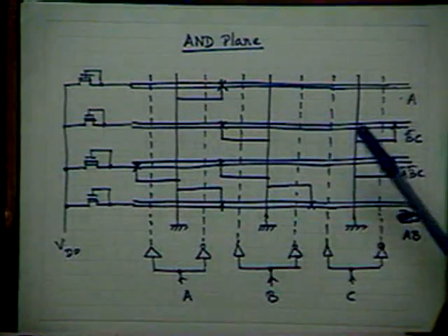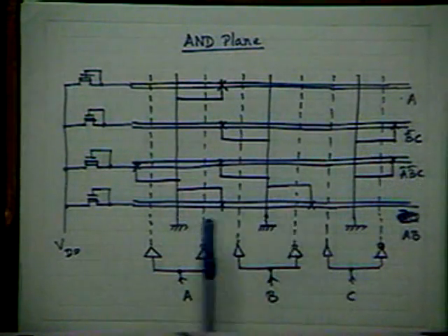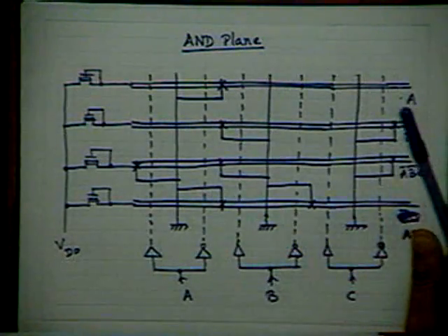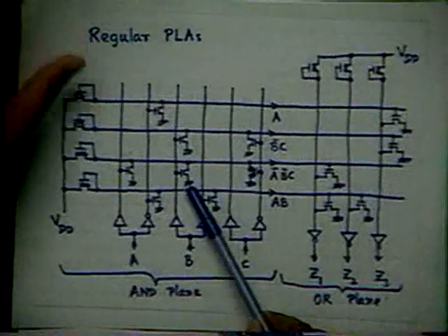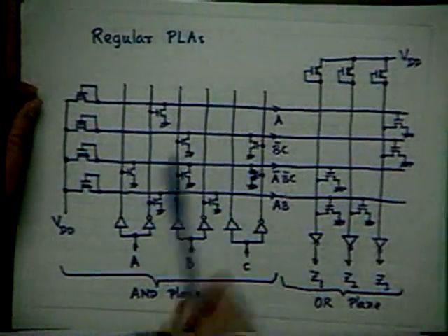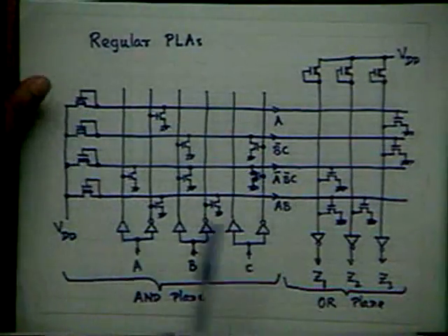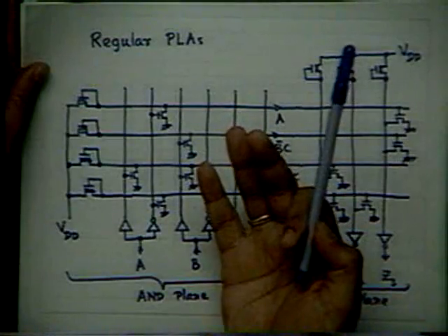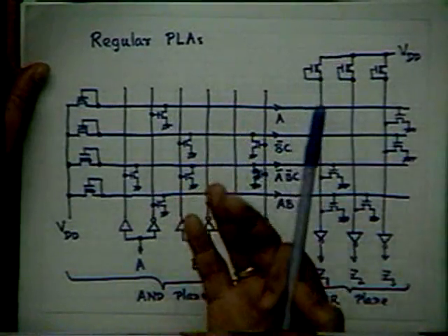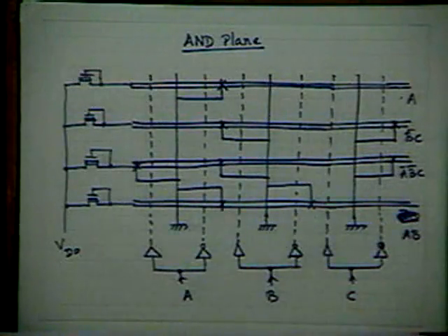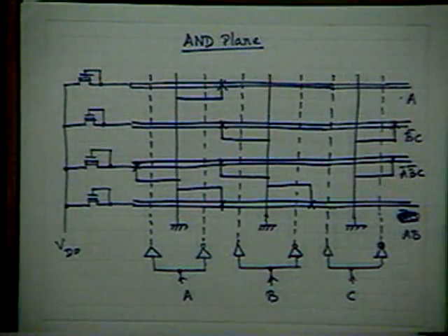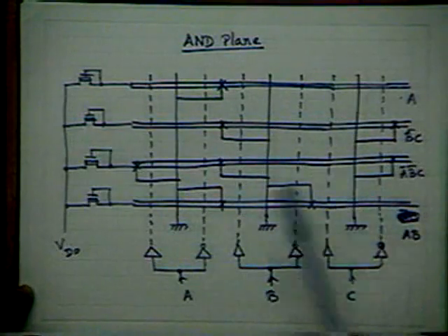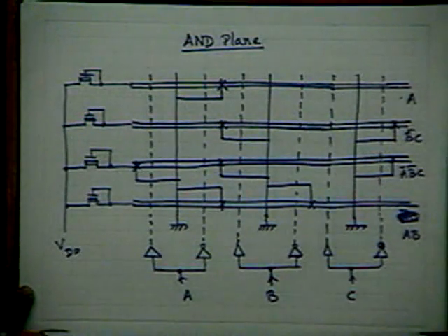So what we have obtained is that you really have to have the hidden ground points, which are shown here. There must be some power line, like the VDD line. In this case there must be a distributed ground line in the substrate. The ground line must be distributed properly and ultimately connected. The stick diagram is an easy approach for showing the layout, which is why we have drawn it through a stick diagram. This way you can really implement the AND.